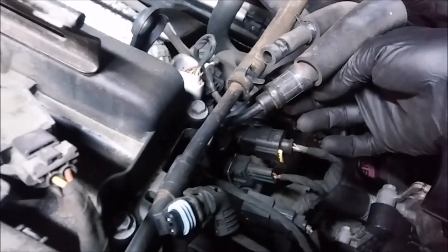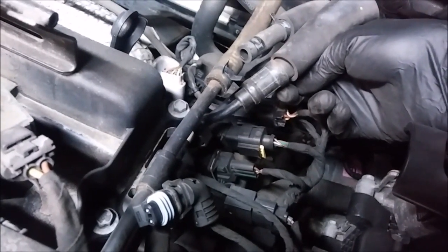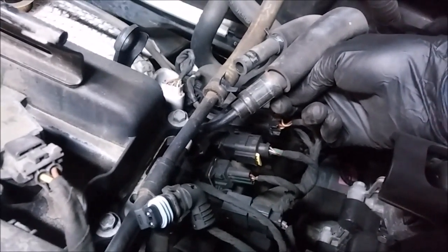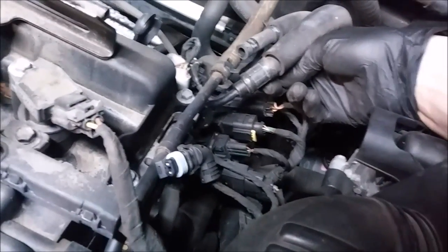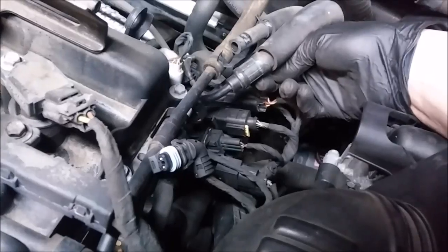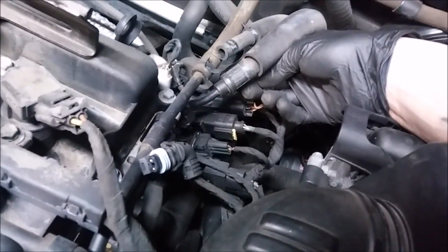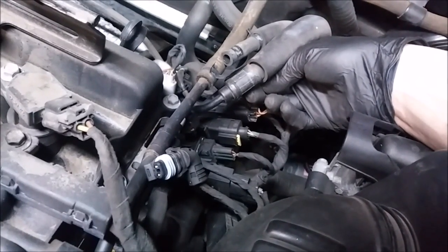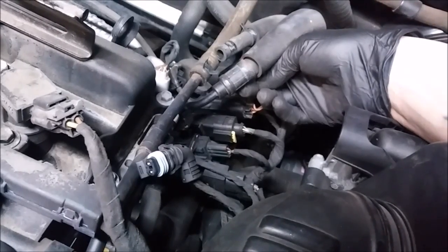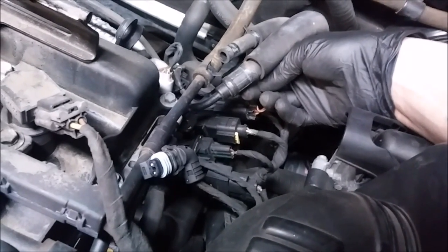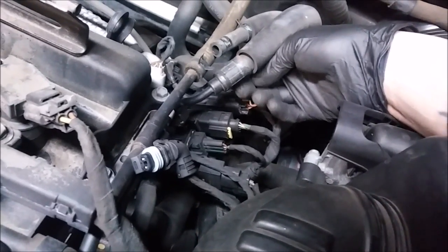You'll disconnect this electrical connector, and you'll place your hand here on the canister side of the purge solenoid, and you'll feel vacuum if it's leaking. I don't feel that on this one, so I don't believe a leaking purge solenoid is our issue. The next easy step I want to do is manually energize this purge solenoid while we monitor fuel tank pressure, and I want to see a response in that, and that's going to kind of prove out that the fuel tank pressure sensor is indeed working. So that's coming up next.